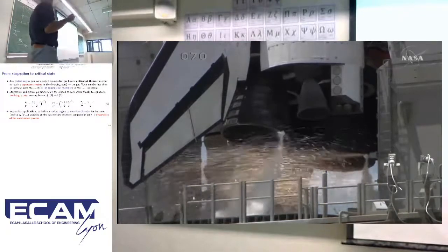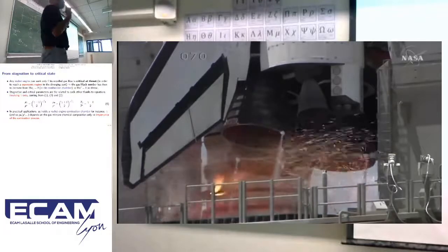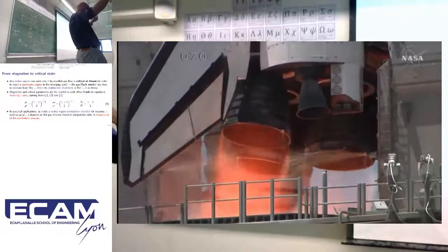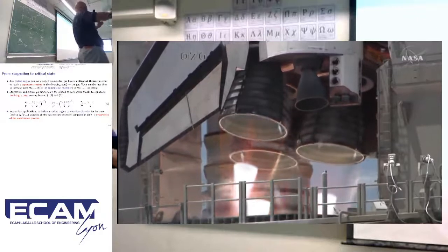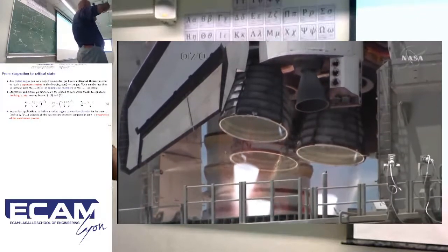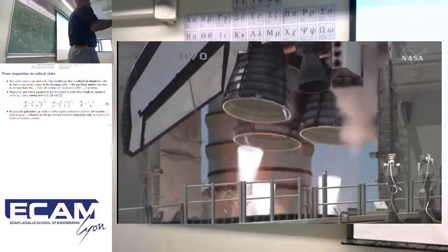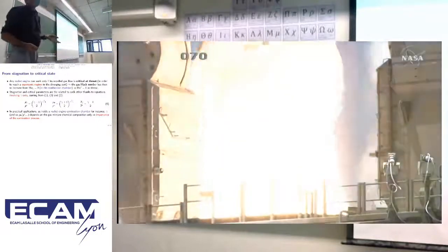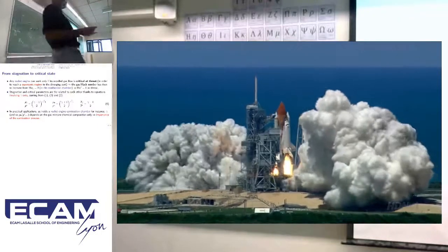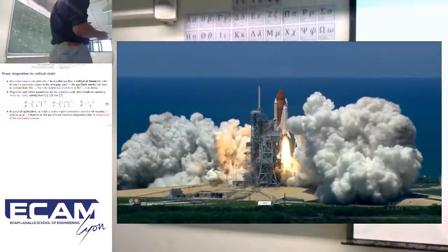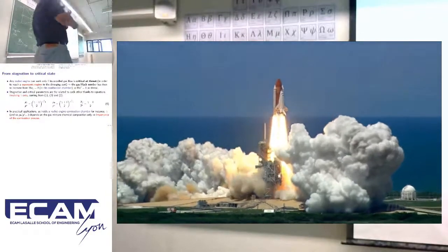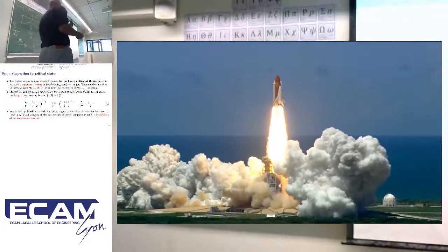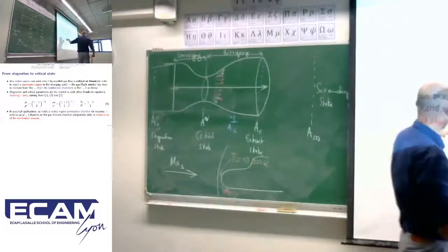And it's once the combustion process is starting, or your turbopump is injecting the fluid inside the combustion chamber, that you will increase the pressure. And once this critical pressure in the stagnation state is reached, your system is really starting. And now we have the flame getting out of the rocket, and you will produce thrust. Okay? And for most rocket engines, it just takes a few seconds to obtain this process. But not enough pressure, no thrust. Okay? And we will use this.